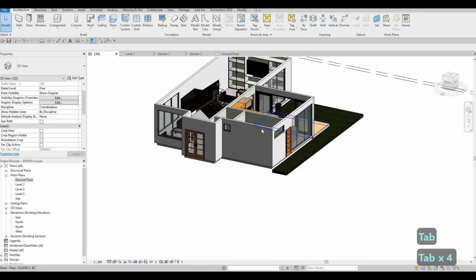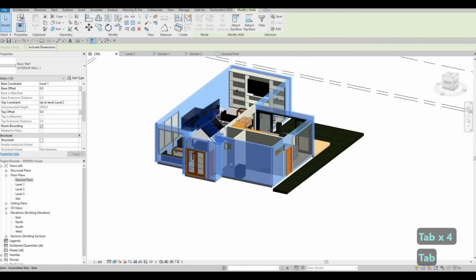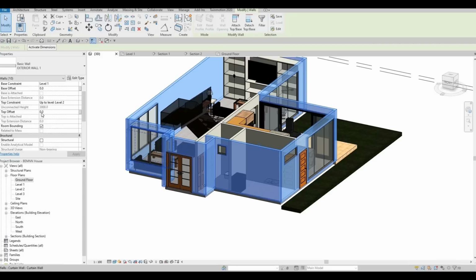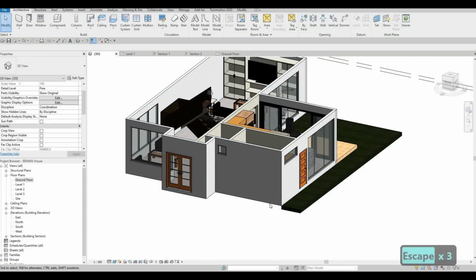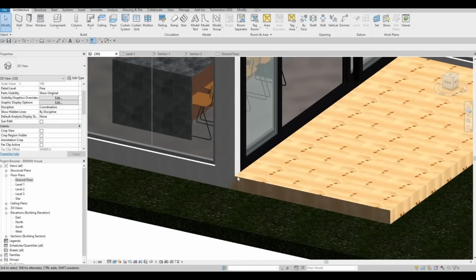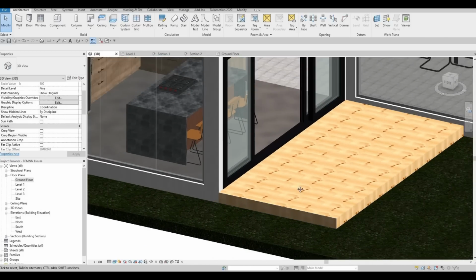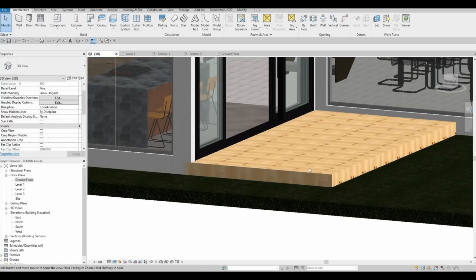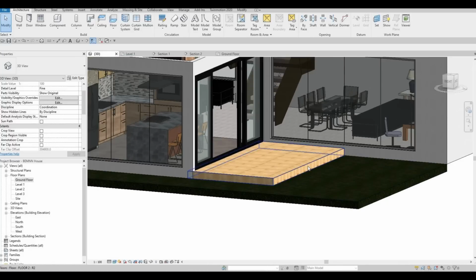It will usually highlight the exterior wall, which is right now all the exterior wall, and then I'm going to let the base constraint be the ground. So it will go to ground, and just like that, it's underground. So what we're gonna do is, because this one has a 200 millimeter thickness for the deck, that's fine.